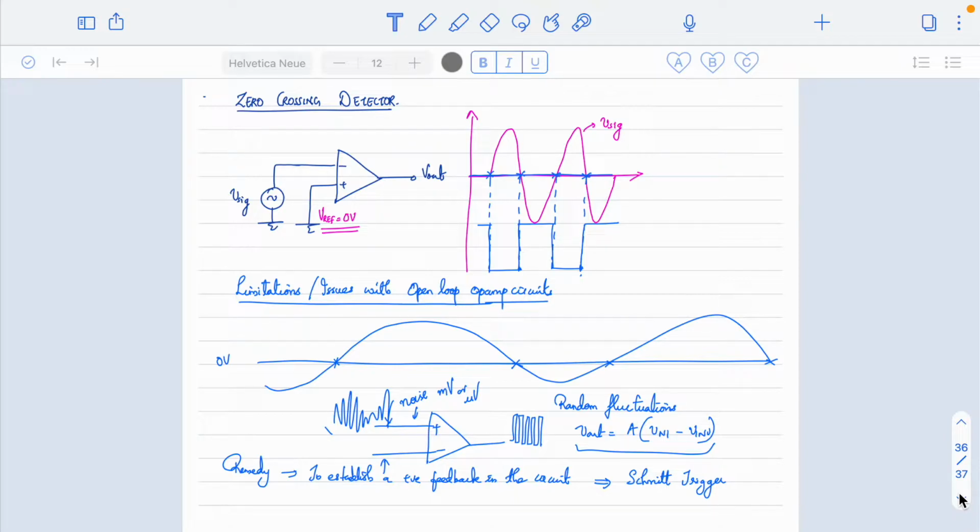The problem is, many a time the noise present at the input terminals is detected as the actual input, and especially in the case of slow varying signals, the noise at one of the input terminals will cause random fluctuations at the output. So whenever such noise is present, it creates confusion on the op amp input side about whether it should respond to that specific input or not.